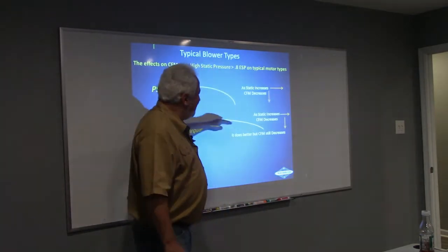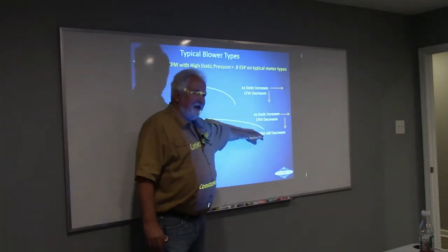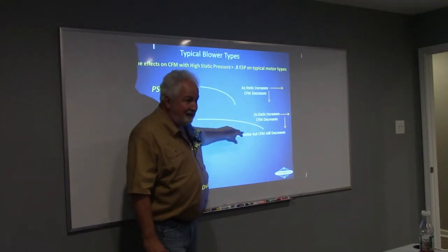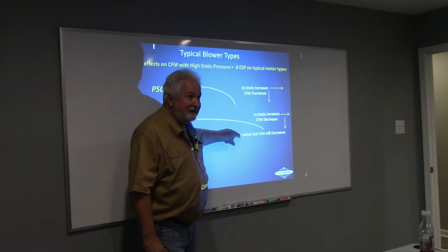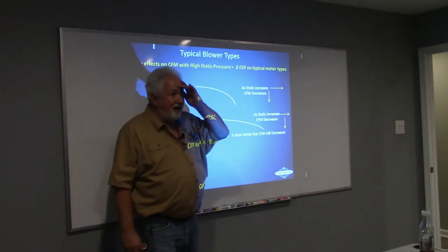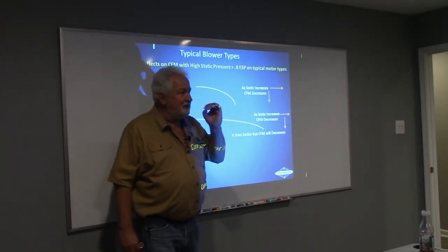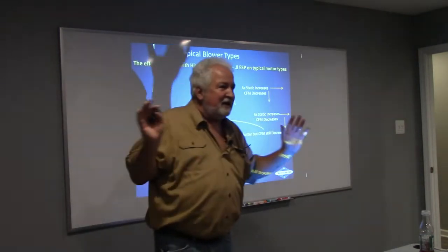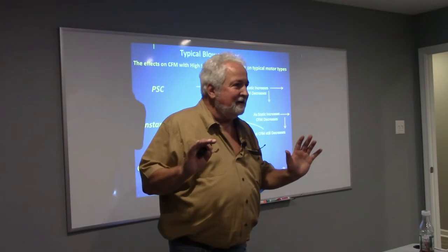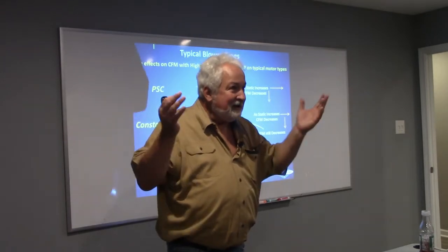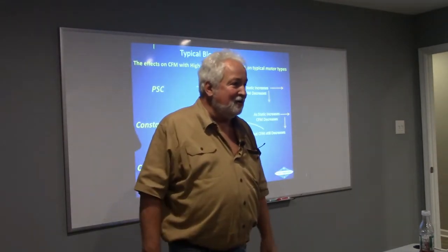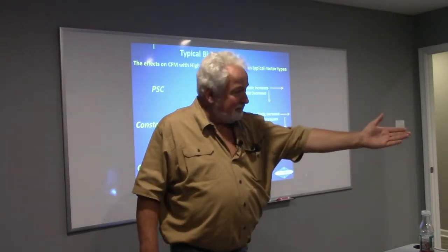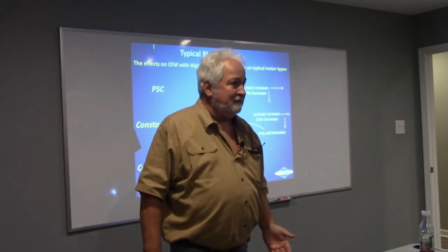So we went from not getting enough air to lowering the fan speed on there and not getting a lot more air, right? You guys are getting this, right? We can't afford it. If I slow that amount of heat down across that evaporator, it's going to cause that evaporator to get colder, and we're going to get liquid going back to my compressor, and I'm going to get a bunch of busted scrolls. Cool?